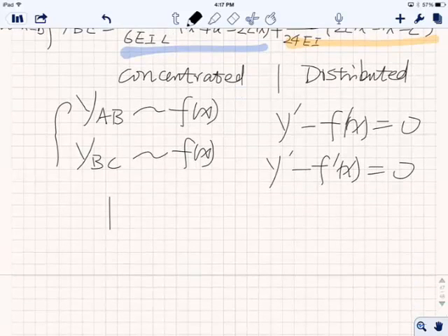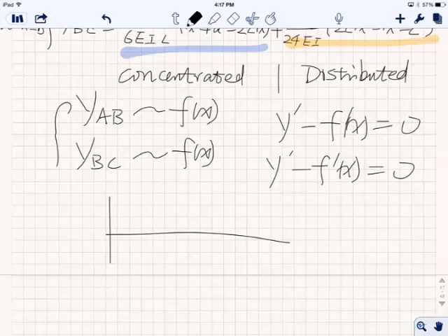Because remember this? If your deflection is not a single function, what you end up with is, for example, it looks like this, and that. So y, x. How do you find a minimum or maximum value? You take the derivative, right? Because when slope is 0, you have either your minimum or maximum value, right? Yes? Okay. So you find an x and then you plug it in to find a y and then compare to see which one is bigger. And that's how you find the answer.